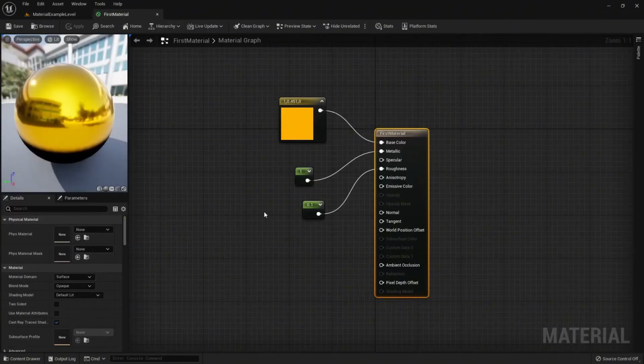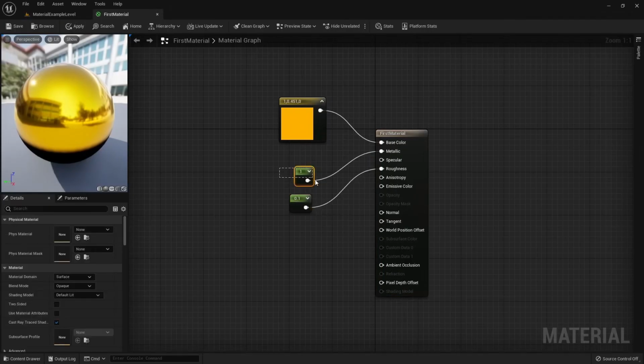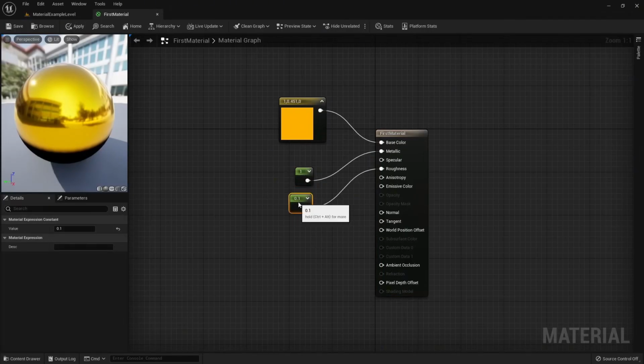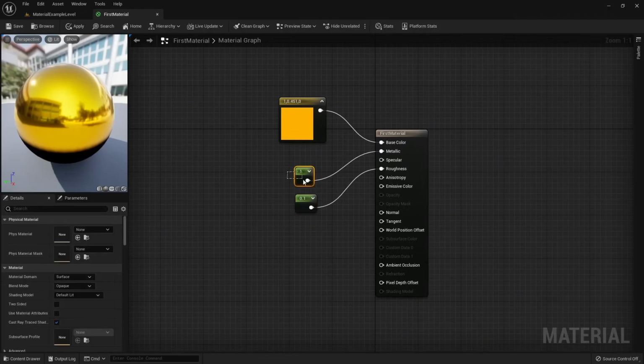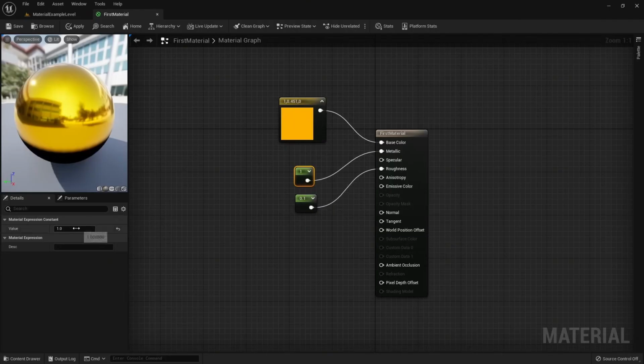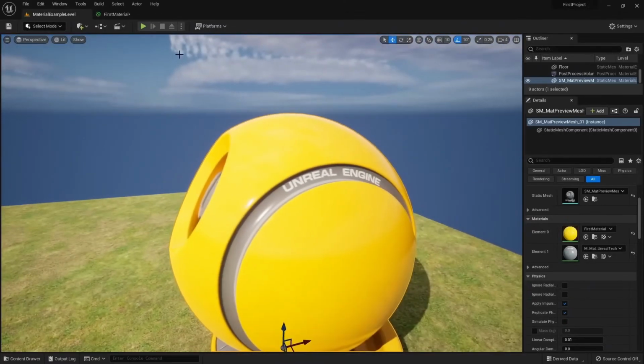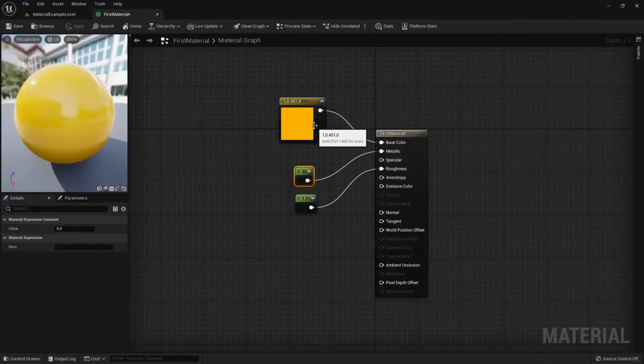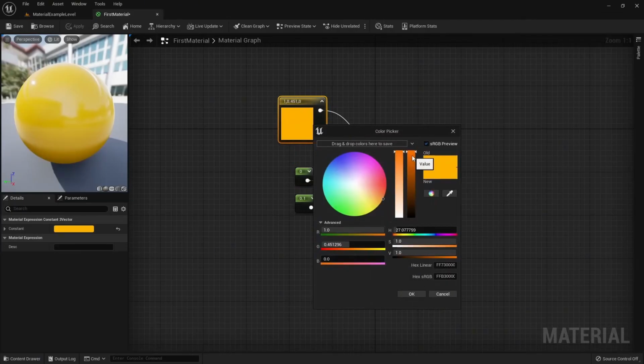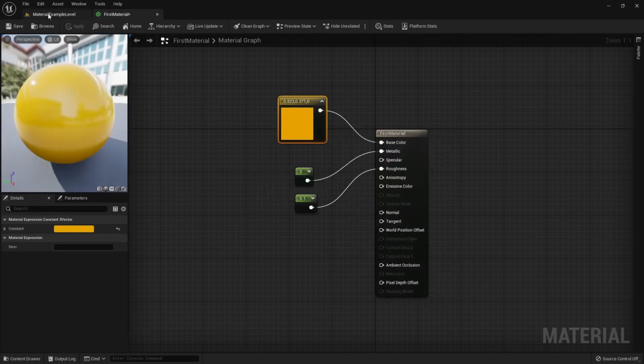So the PBR sliders we were just playing with are the metallic and roughness values right here. So those sliders correspond with these values. So hopefully you understand exactly what they do now. Now I'm going to make a slight edit. So for metallic, let's bring it from 1 to its default value of 0. So that's kind of like a plastic material right now. And also, I think it's a little bit too bright. So double clicking on the color, I'm able to decrease the brightness by playing with its value. So bring it down a little bit, press OK, press apply.